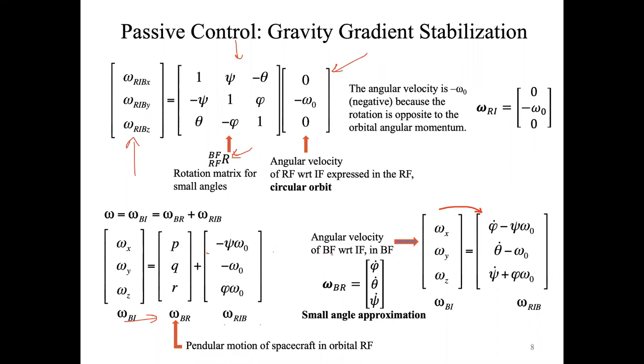The main problem here is that we are trying to linearize the dynamical equations of the attitude in order to have a quick integration of those angles. That's the reason why here we are assuming small angles.